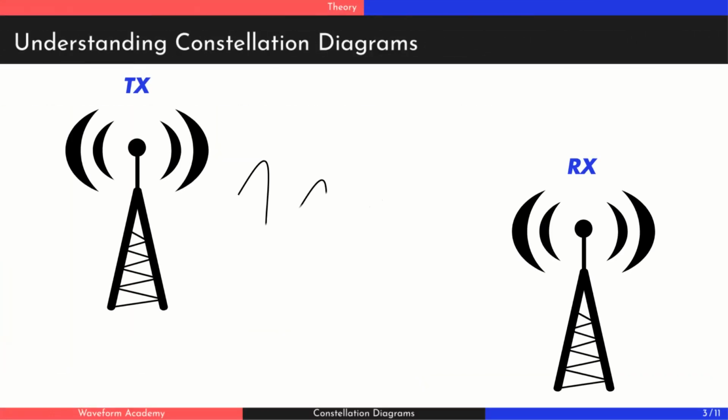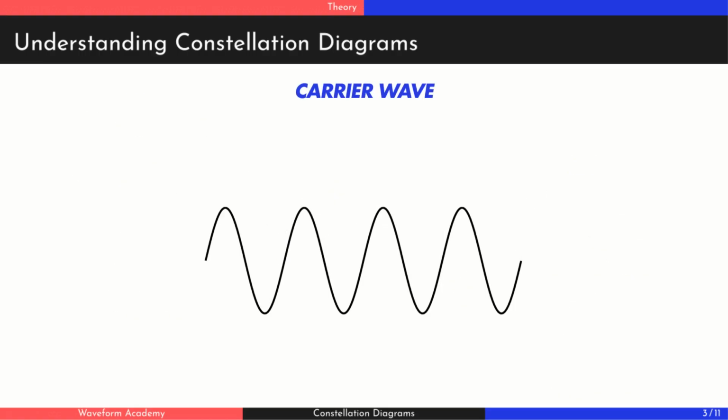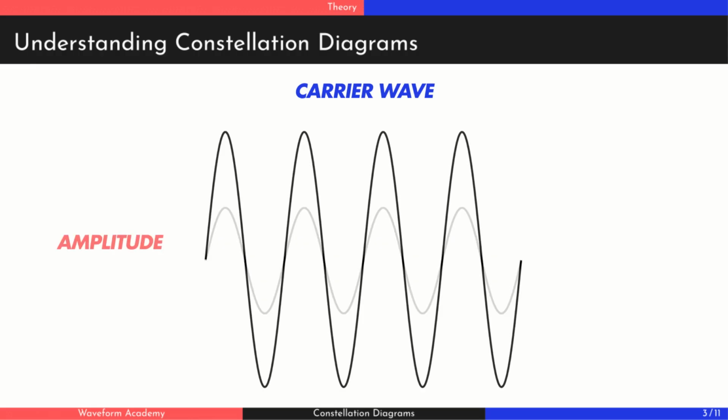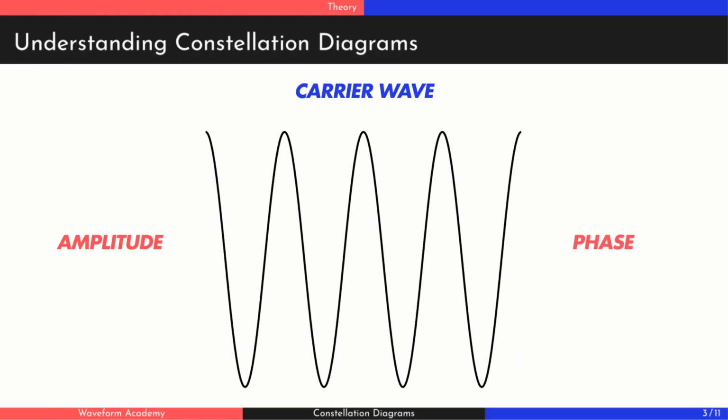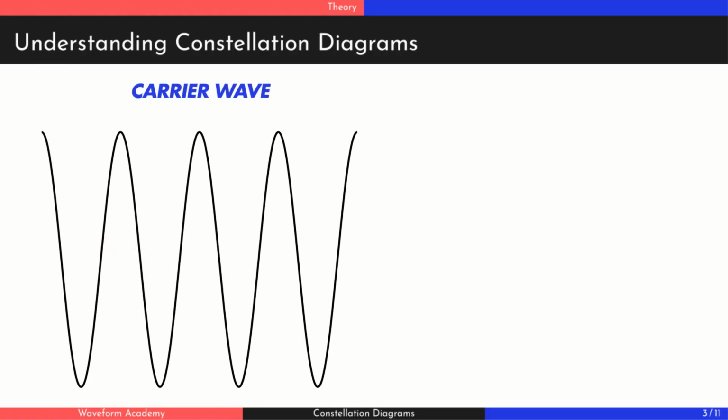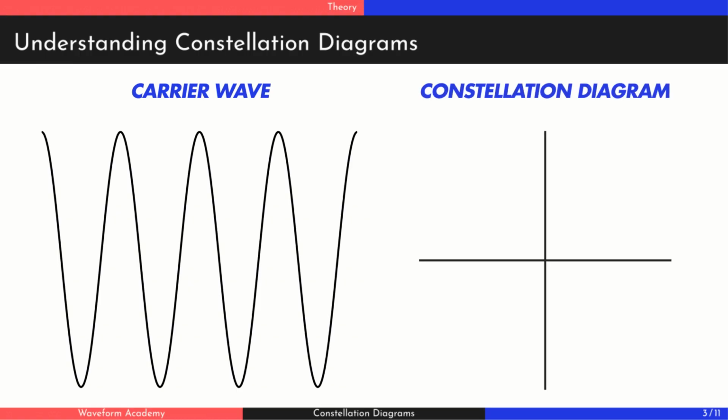To transmit data wirelessly, we rely on electromagnetic signals, which can be pictured as simple sine oscillations. However, a static, unvarying cycle is empty. It carries no information. To pack it with data, we must shape the wave. The two key properties we can modify are its amplitude, the signal's peak height or power, and phase, its position in the cycle. Before transmission, the two devices agree on a codebook, a mapping that links specific combinations of amplitude and phase to bit patterns.